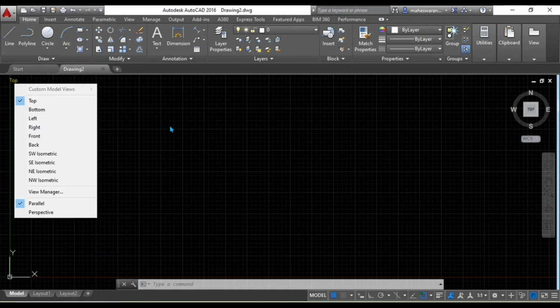Today let me draw two diagrams, a prism which is resting on a vertical plane, which means, for example, if I consider a hexagonal prism, the shape hexagon will be on the front view and the other view, the height, will be seen on the top view. Similarly, I'll go for a pyramid considering that it is resting on its base on HP. Let me consider a pentagonal pyramid. If I consider a pentagon, you have to draw the pentagon in the top view and the front view will be its axis.